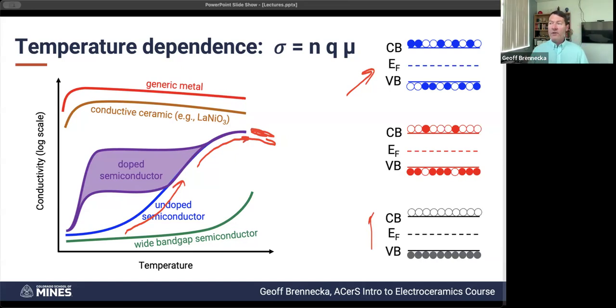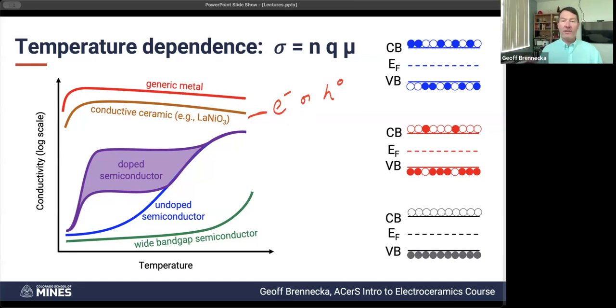So for conductive ceramic here, the schematic, the little cartoon that I've drawn, it would essentially be the same for any electronic or hole conductor. So as long as it's a high mobility electronic species. So for this, yes, I mean electrons or holes are the dominant carrier. And the reason for that is that those are going to be scattering dominated rather than hopping dominated.